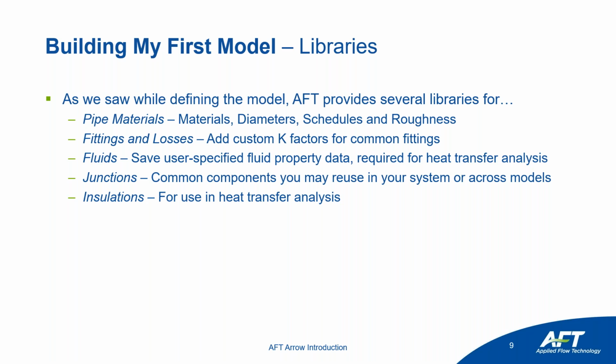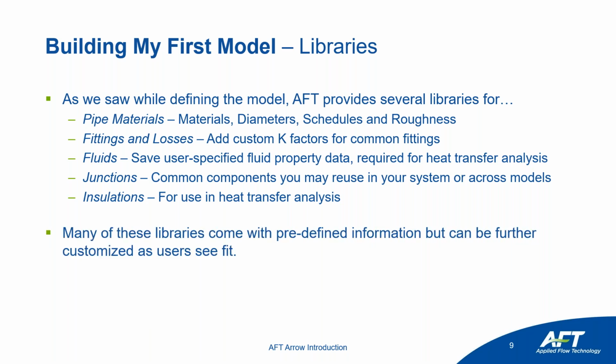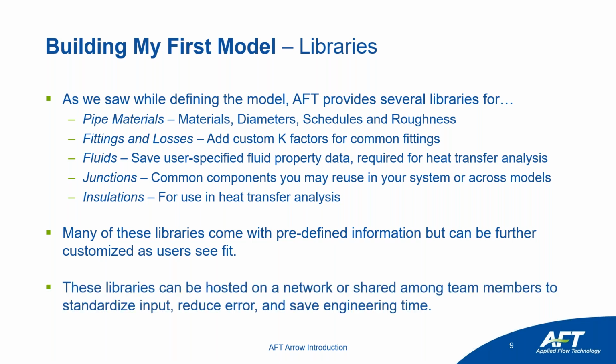And then finally, as we look at heat transfer analysis a little bit later in the presentation, you can also adjust things like the insulation on your piping. As I mentioned, most of these libraries are going to come with predefined information, but all of them can be further customized as you see fit and as you need. These libraries are also valuable because if you invest the time in them up front, it's very easy to share those across different users or across models and different projects. You can host them on a server. And again, the intent of having this standard library of input is you're going to standardize that input, which reduces any input error, and then obviously it's going to save you engineering time instead of always looking up the same K-factor losses.